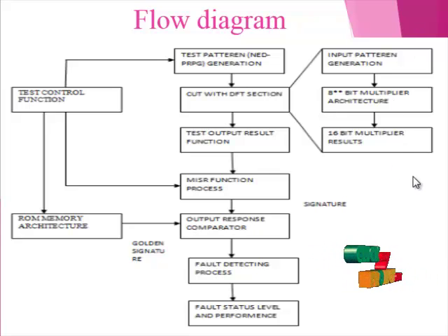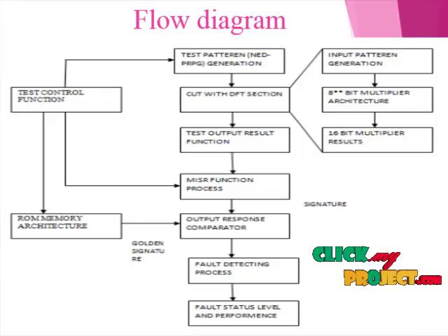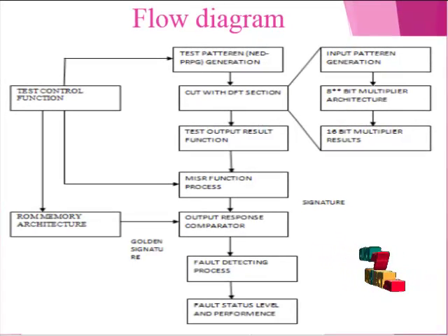The test pattern generator generates the test patterns for the CUT. It is a dedicated circuit or a microprocessor. The patterns may be generated pseudo-randomly or deterministically. The multiple input signature register, or MISR, is designed for signature analysis, which is a technique for data compression. MISR efficiently maps different input streams to different signatures with a very small probability of aliasing. MISRs are frequently implemented in built-in self-test designs in which output responses are compressed by the MISR.